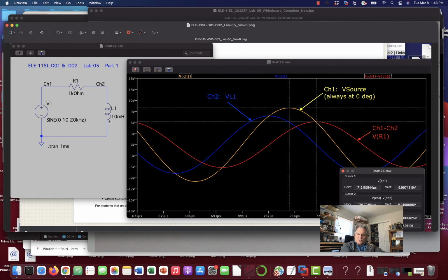If you have no resistance in the wire of your coil, then it's going to behave like an ideal coil, and you always have 90 degrees phase shift. But it's very typical for coils to have some resistance because they're made of wire. And not all inductors are coils; there are other types, but an inductor is usually made of wire, and that wire has resistance. Therefore, the inductor is not a pure inductor. A little bit of resistance is experienced. But don't worry about that.